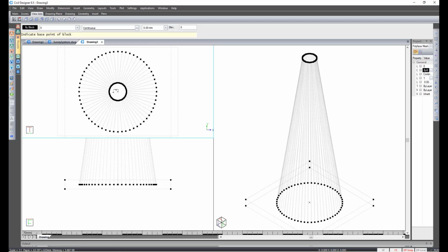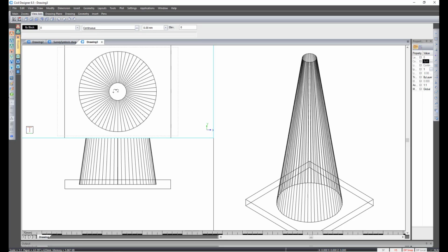Again, I'm going to press X on my keyboard to go to the center of our cone and enter. Press escape. Reading the prompt, it says indicate the lower left corner of snip box or press space to skip. We don't want to snip anything, so I press space. Press escape. You can then save this as a drawing.